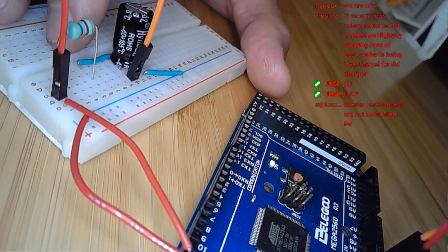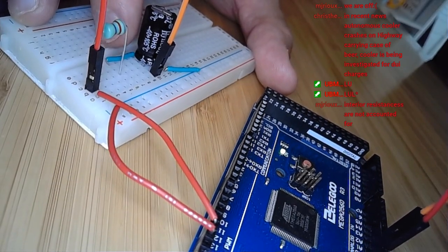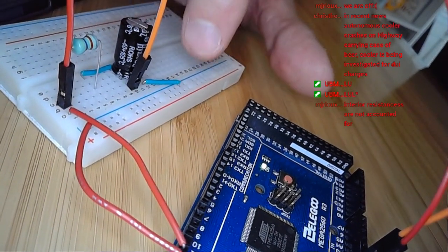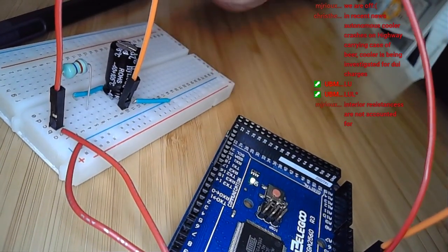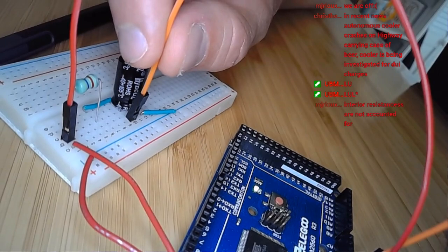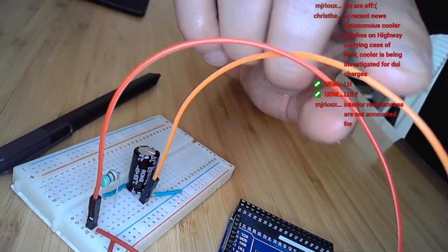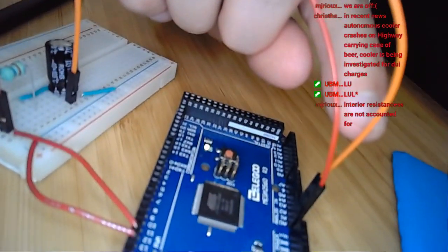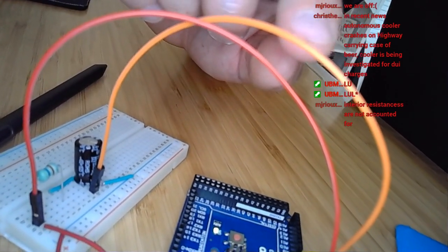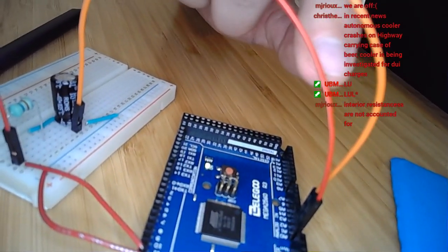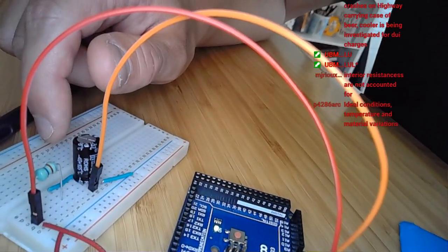Yeah, I think you're right, MJ. If you see this little teal wire that connects the inductor to the capacitor, and once again it connects the capacitor to the ground, and this orange wire is what we're reading the capacitor voltage with. But look at this, the current has to travel all the way to the Arduino. And this wire has some resistance. Oh, and by the way, the source voltage has to travel through this red wire all the way over to our circuit.